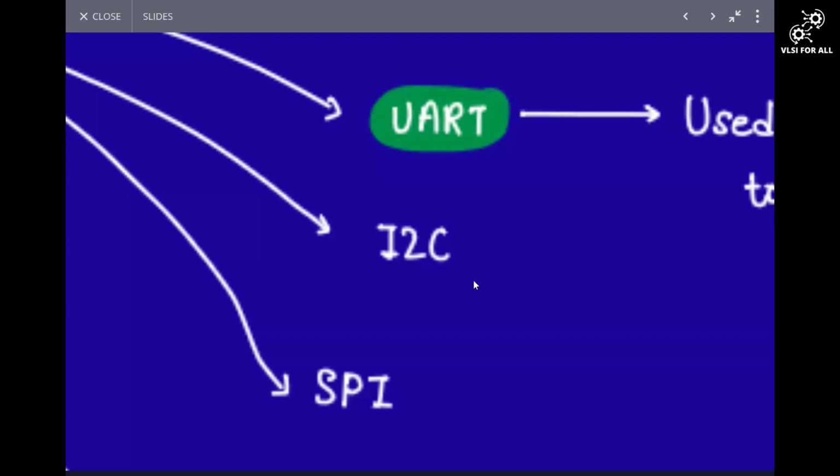32 minimum, yeah. So all these embedded chips, they are sensing many things within the car, and they are actuating things based on the temperature that they receive. They may start to run some coolant system, right? So all of this is happening by communicating between many sensors. These communication protocols, especially the CAN protocol, you use for automobile embedded systems, right? For generic purpose, for generic sensors, you use SPI, I2C, and UART.